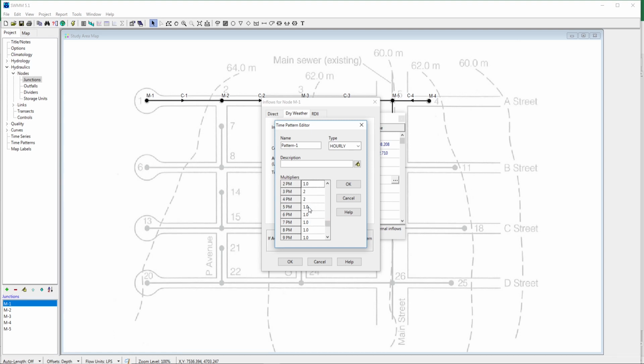So when we are setting up our own system of the demand or of the sanitary load pattern, we have to think that the average of this 24 hours duration must be equal to 1, because in 24 hours the average flow is being supplied, but during 24 hours sometimes it is more and sometimes it is less.